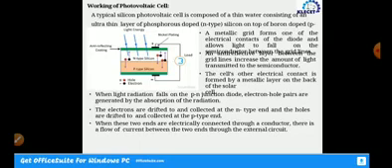The construction, as I already told, is very simple. It includes a metallic grid, a silicon wafer, and an ultra thin layer of p-type and n-type silicon respectively. Below that I have the metallic layer, which acts as an electrical contact, and the anti-reflective layer, which is coated with titanium dioxide to improve the intensity. This much you can write with respect to construction in the examinations.